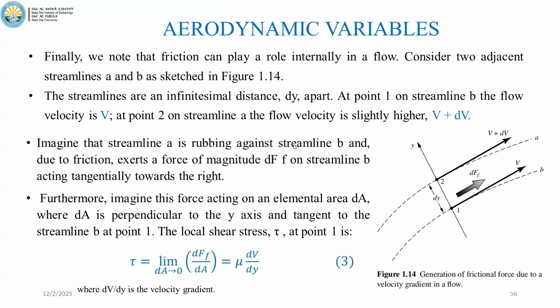And from that, the shear force can also be obtained from the parallel plate experiment, to determine the shear using dynamic viscosity and the velocity gradient. And shear force is just a force. The shear stress is the shear force divided by the shear area. Okay, shear stress is equal to shear force over shear area.